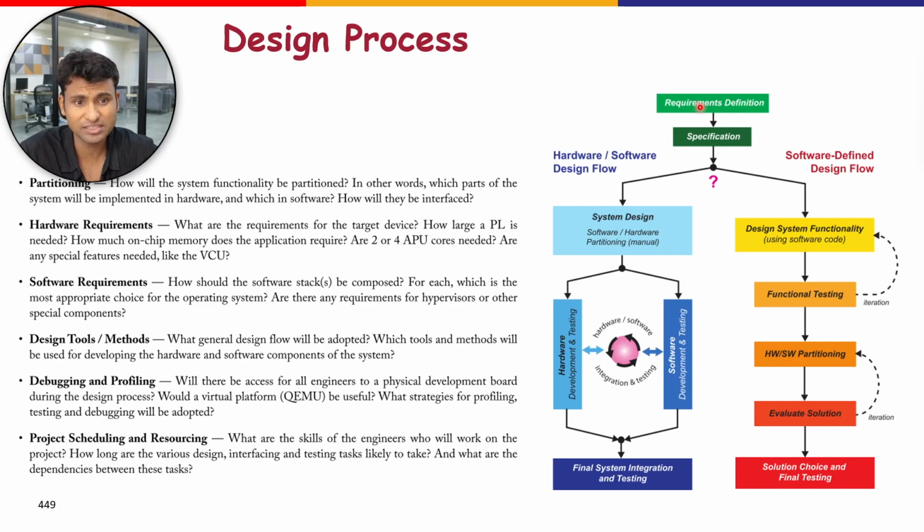So getting a requirement and specification is the most important task. When embarking on a Zynq MPSoC system design, a major initial task is to generate the set of functionality and performance requirements. This will capture the target features of the design, and ultimately it will influence all the design choices that follow. So the captured requirements can be developed into a formal specification of the system. With the end goals established, this will inform the selection of target device, estimates of the design effort and the resources required, the composition of the design team, which might include hardware, software, system engineers, algorithmic specialists, etc., the choice of design methods and development tools, as well as the general planning and scheduling.